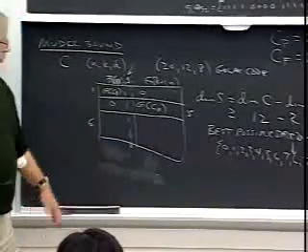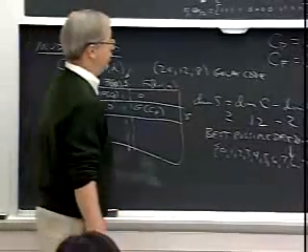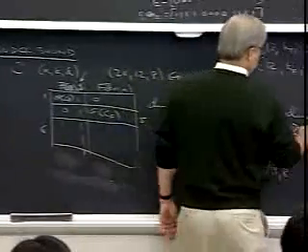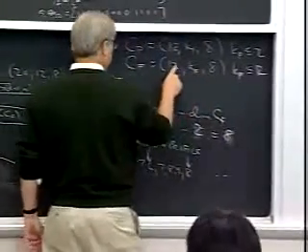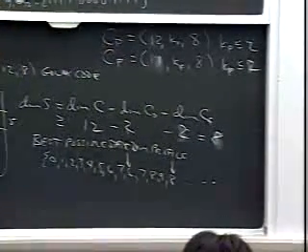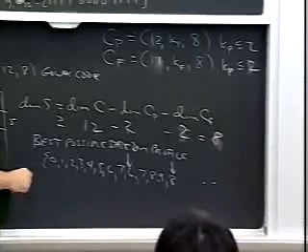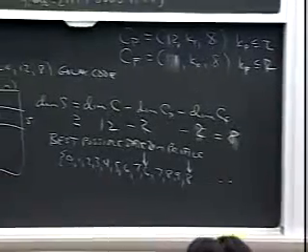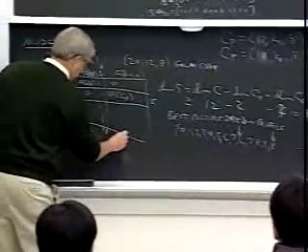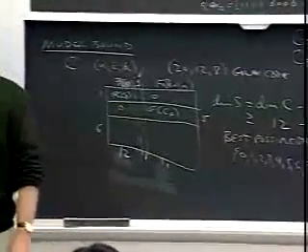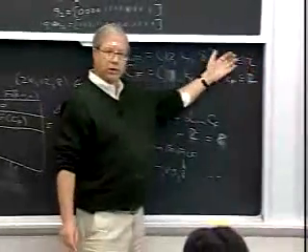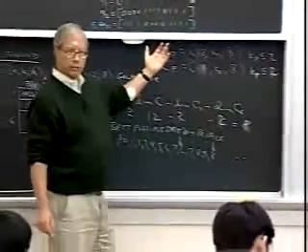Okay, so this is what the matrix looks like for this, and the effect over here is that the future subcode now is 1 unit shorter. So let's do the same calculation here. If we look at a time where we have 12 in the past, this one time, the 13th symbol time that we're actually looking at, and then 11 more in the future. The past subcode, again, could have dimension up to 2 because it has length 12 and minimum distance 8.